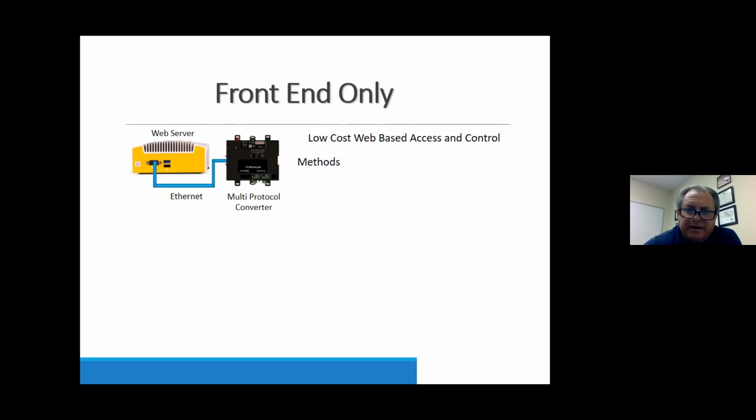So we're talking about light DDC, right? Integration to bigger projects and things like that. Yes, there's a lot of time and labor involved, but when we're talking about light DDC, what we want is easy access to the integratable points of control from an application or from a piece of equipment. So we don't need servers that are handling an entire school campus. What we need is a small server.